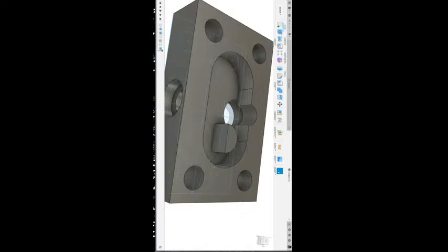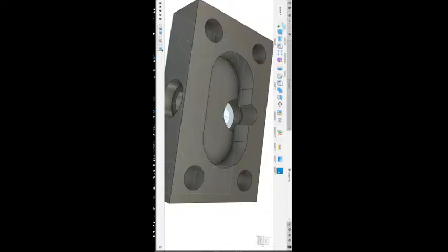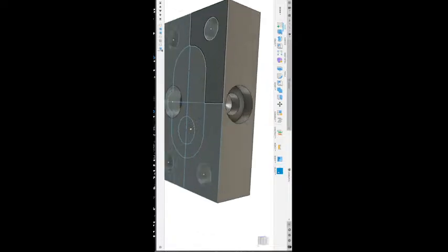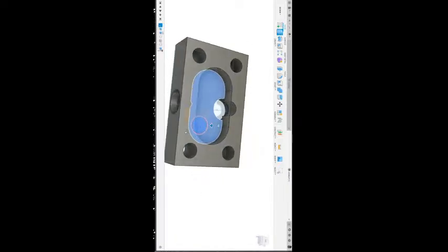So we are gonna exclude it. How are we gonna exclude it? By hitting E. It's going to be 1.5 mm from this object, minus 1.5.